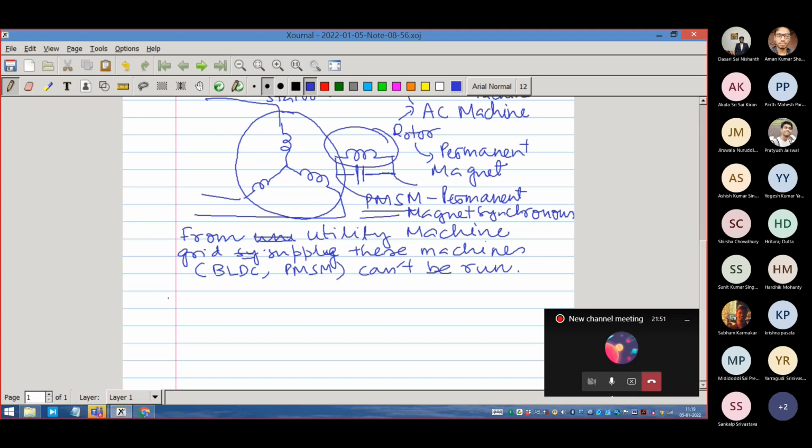Earlier there was no diode rectifier, so it was a mechanical rectifier. So commutator and brush act exactly like a mechanical rectifier. People were brilliant at that time also. They understood, even though semiconductors were not available, they made a mechanical rectifier. It complicated the machine immensely, but the job is done. And the initial development of different industries relied on the DC machines for quite some time.